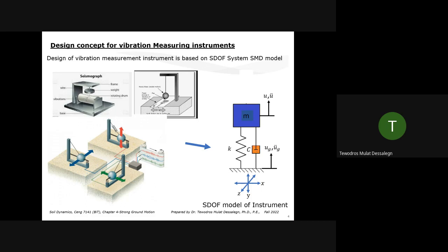When a vibration occurs, the framing, everything moves, and this is relatively stable, doesn't move. So it makes a scratch, we get our seismogram. And this is for one direction. You can have this setup in 3 directions and get the output in 3 directions. All can produce this. And this can be digitized.